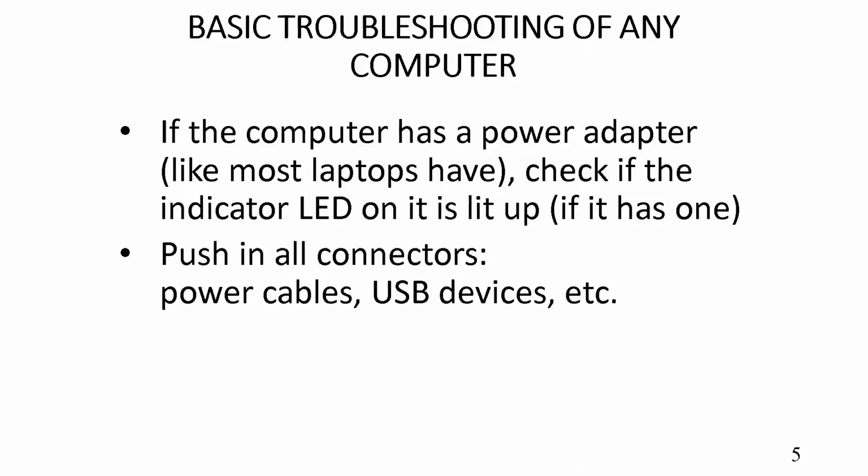Next, push in all connectors. Especially power cables and USB cables have connectors at the end that go into your computer. Push them all the way in. If they're not pushed all the way in, it will cause problems for your computer. For example, if a USB 3 connector is halfway out of its USB port, it will become USB 2 or intermittent and cause you problems.